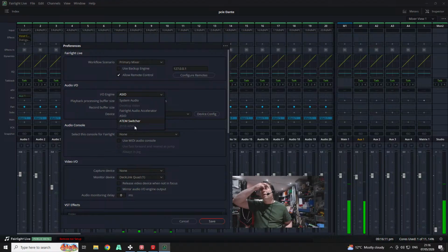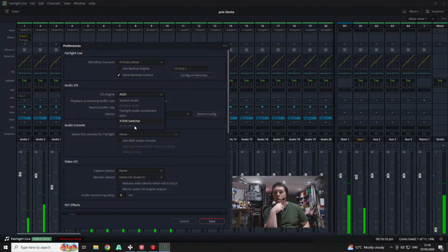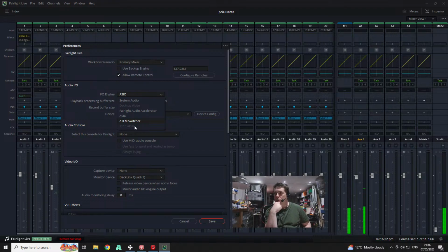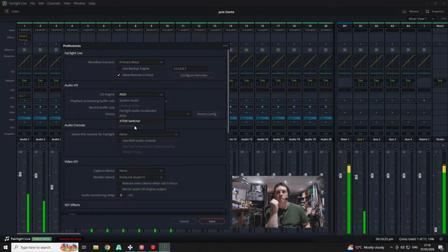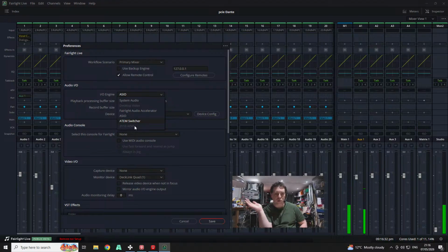So the panels themselves don't process any audio. They're just a remote for the processing engine. If you're in a 2110 environment, you potentially would have your control network and your 2110 network converged. So you just have a cable going from your switch network to your audio processor and a cable going to your surface, and it just works. But in terms of different types of traffic, it's control only to the panels.